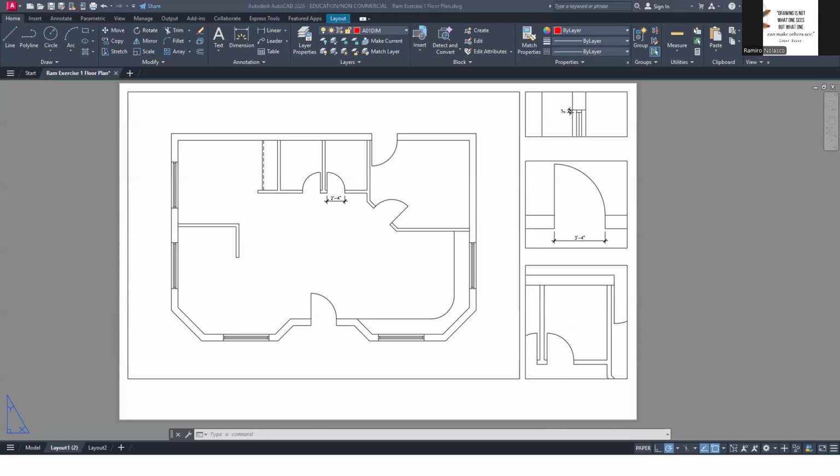And then, and only then, do you go to the viewport, maximize, and then add the dimension. See, the dimension will be added in the proper text, and make sure show annotation objects is turned off. Make sure add scale to annotative object is turned off. Okay? And then minimize.